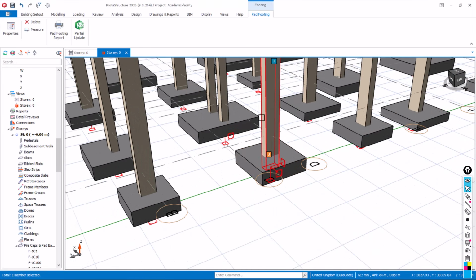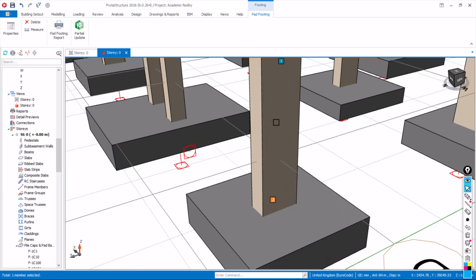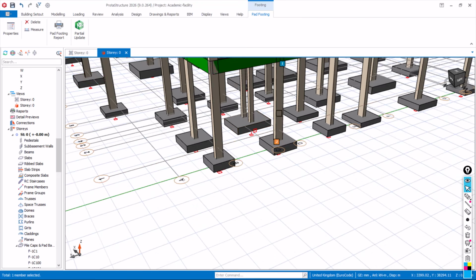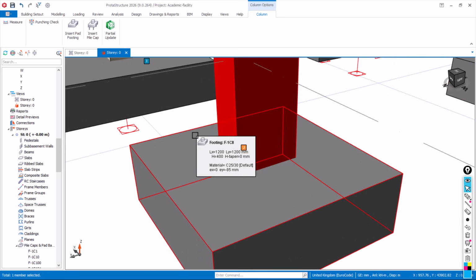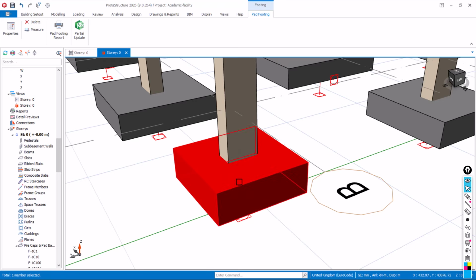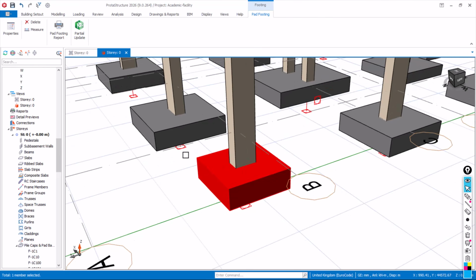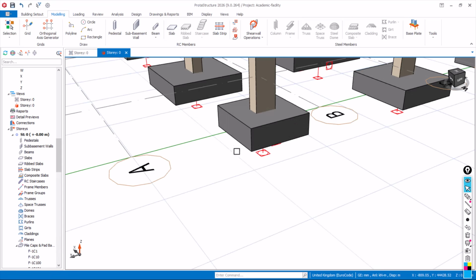So when this happens, that gives birth to what? An eccentric footing. And that becomes very, very difficult because now all the weight will be on one side, and that will cause what? Overturning on the other side of the footing. And since in that case, when all the loads are at one point, what happens? It will give birth to non-uniform soil pressure below the footing.